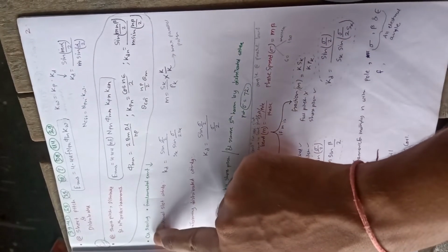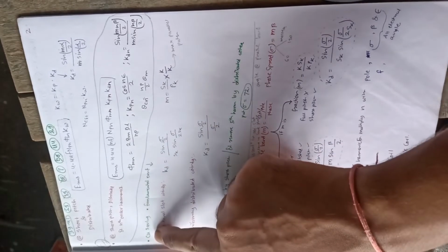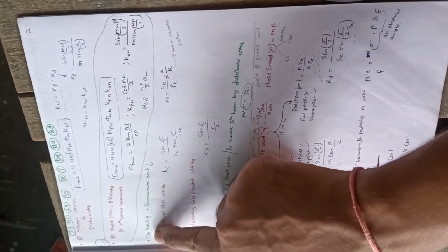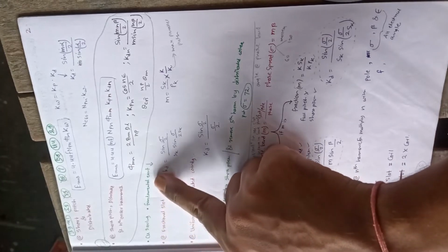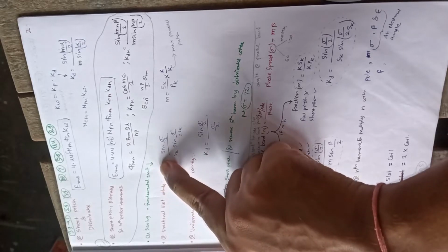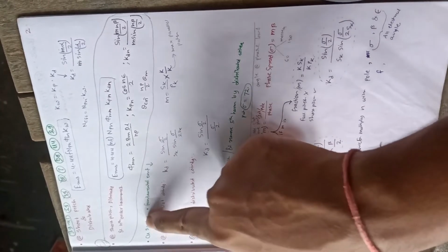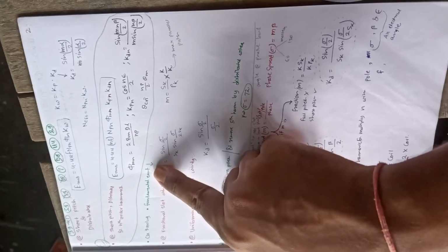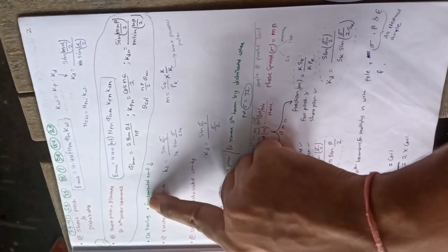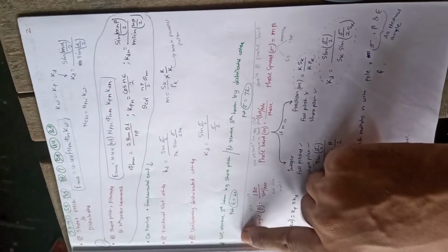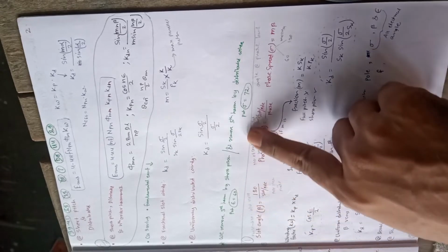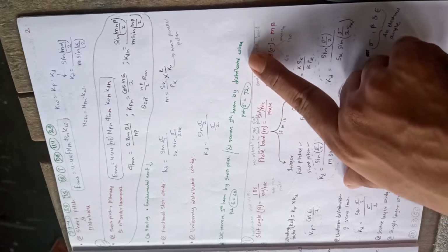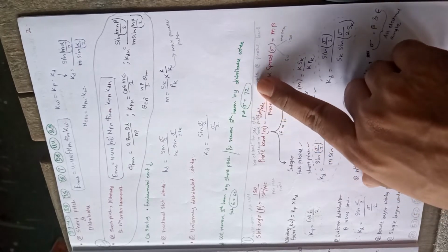Keep in mind that after doing these things, we have the advantage that copper saving is introduced, but the only disadvantage is that overall EMF is reduced, but its quality is good because it is harmonic free. That's why after doing this we get harmonic free, reduced EMF, and copper saving is also done. So to remove third harmonic by short pitching, put epsilon equals 60 degree. To remove fifth harmonic by distributed winding, put sigma equals 72 degree.